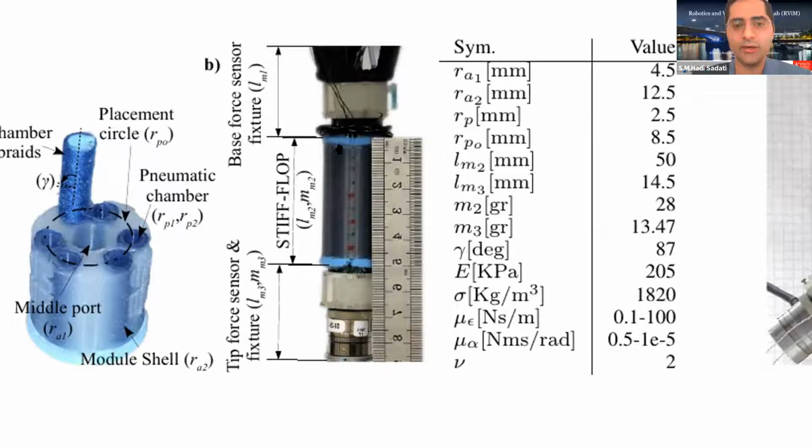It's 50 millimeters long. The active part is 44 millimeters. So you have two silicone caps at both ends that you don't have any control over. And when you calculate the accuracy in percentage, you divide the absolute error of the tip by the length. Usually, divided by that small length, you end up with large errors.